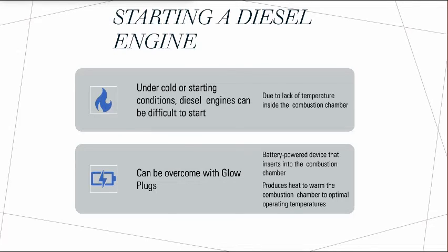Starting a diesel engine is a lot different than starting a gas-powered engine. Whereas a gas engine starts when the fuel is ignited by the spark plug, the diesel engine relies on the heat created by compression in the chamber. The most common method for starting a diesel engine is through the use of glow plugs. Like an air intake heater, the glow plugs operate off the power of the vehicle's battery, and this pre-warming process brings the air in the combustion chamber up to a temperature conducive enough to cold starting. Sometimes, such as during cold weather, the diesel fuel needs the aid of an outside source of heat to reach the appropriate temperature to start.